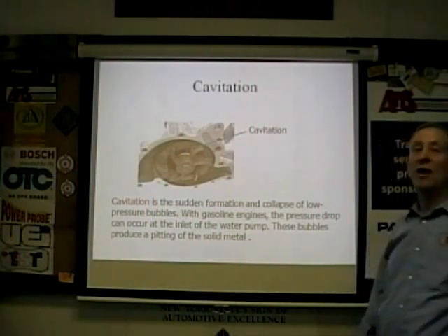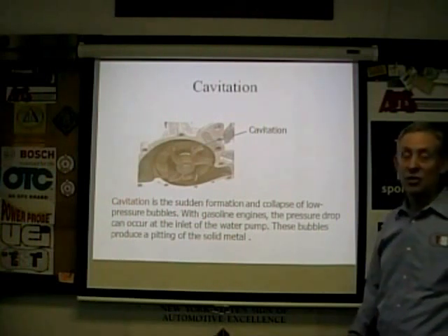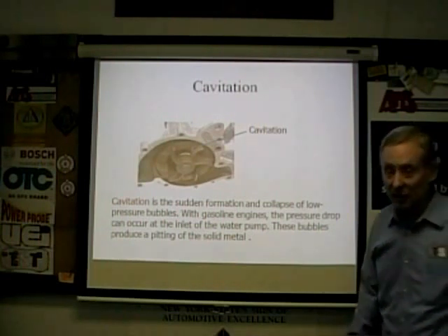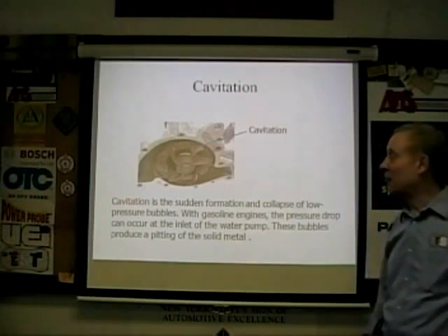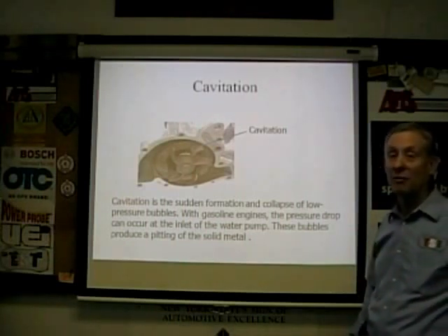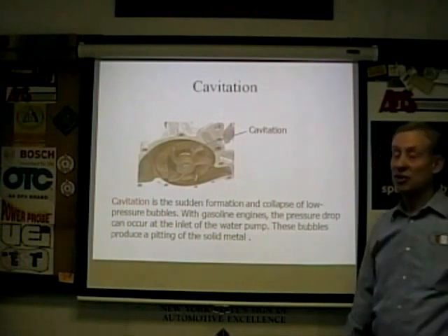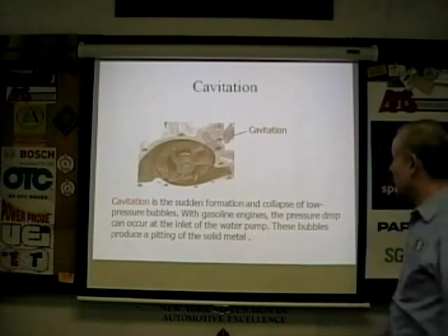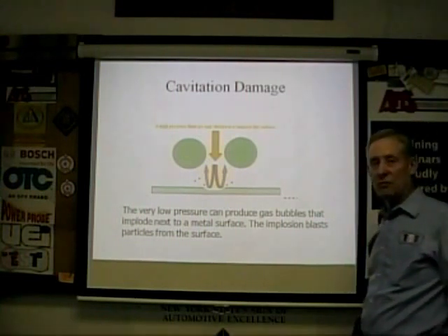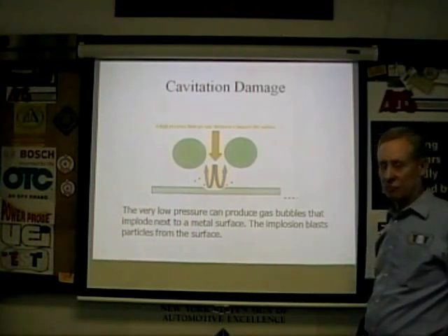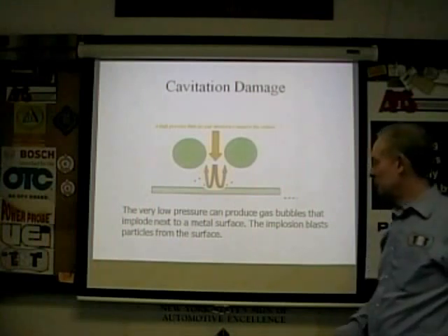And you have to look for why there's air getting into that system. You may have a hose clamp or something that's letting air get sucked in on some low pressure area. You might have a problem with a radiator cap, common problem. Whatever it is, you're aerating your coolant, and it's a problem. Look for collapsed hoses, which sometimes will tell you you have a bad cap. That's one of the things that is good to take a peek at.